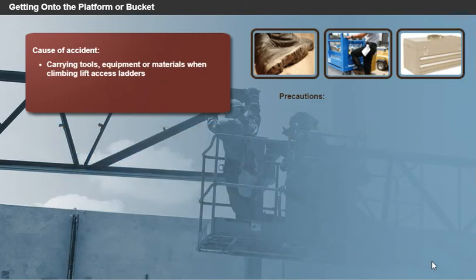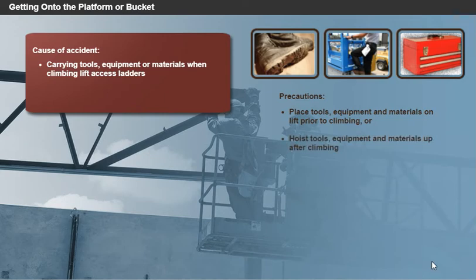Carrying tools, equipment, or materials when climbing lift access ladders. Place tools, equipment, and materials on the lift prior to climbing, or wait until you've climbed onto the platform and then lift or hoist these items up using a rope.